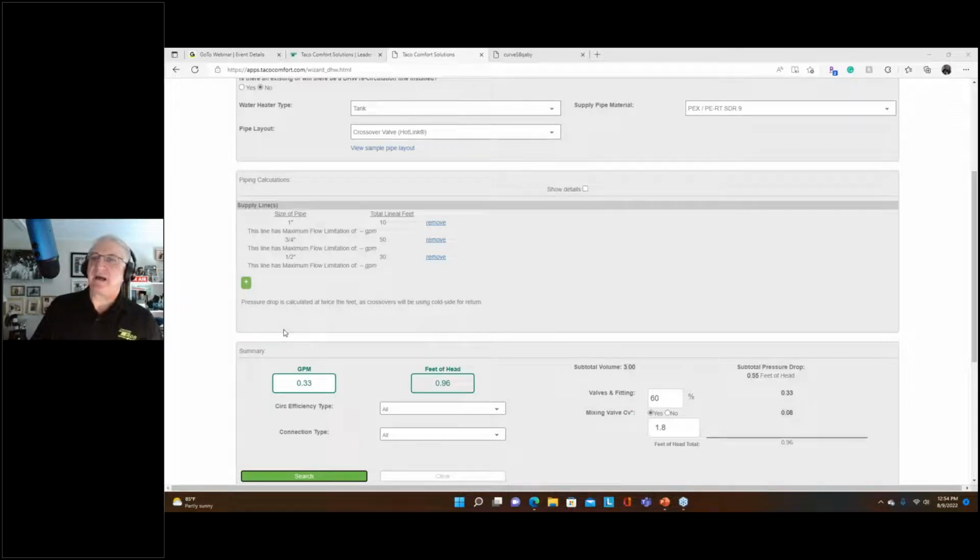Can we put in a timer? We certainly can. We sell circulators with timers on them that you can simply set the dip switches and tell it when to come on, when to turn off, etc. The challenge with timers is twofold. Number one, setting them up. Who does it? I've heard contractors say, well, we set it up for our customer.